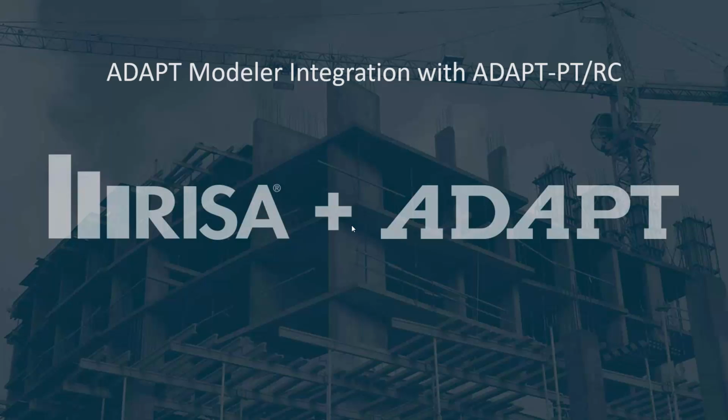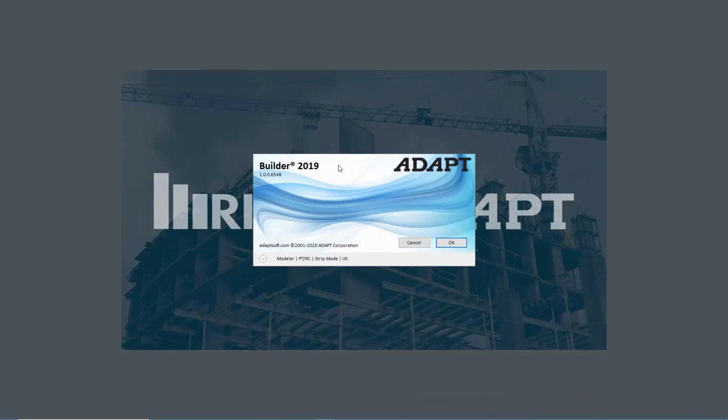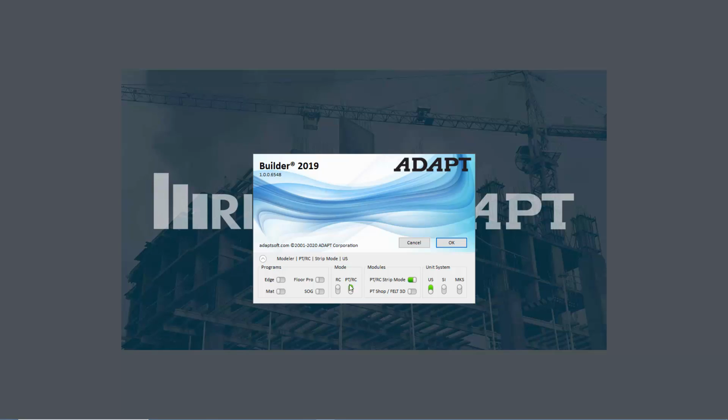In this video, we're going to explore the use of Adapt Modeler and its integration with Adapt PTRC to determine post-tensioning forces and profiles for two-way slabs. We'll be using Adapt Builder 2019, and we want to make sure in the opening screen here that we select the option here for PT strip mode. That allows us to export the strips that are created to Adapt PTRC.